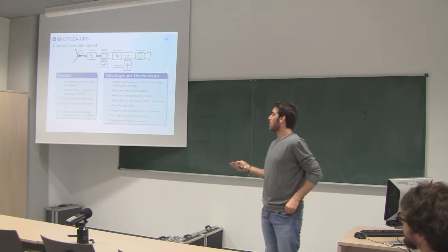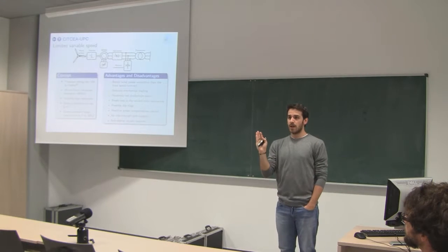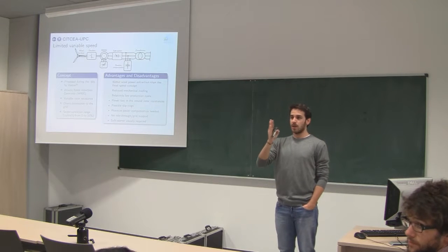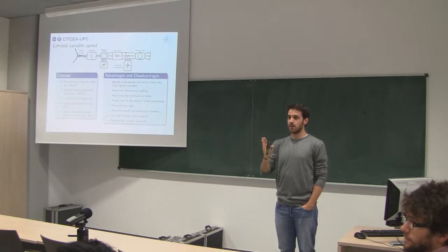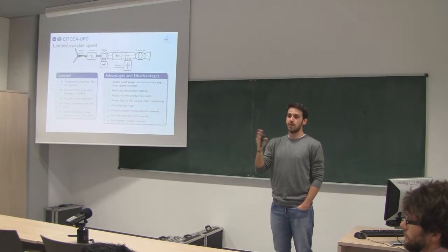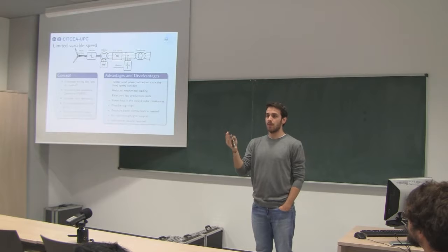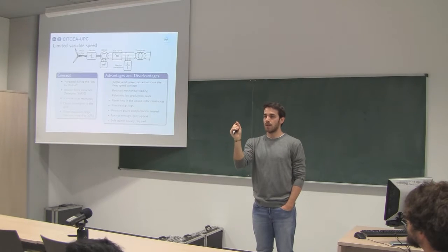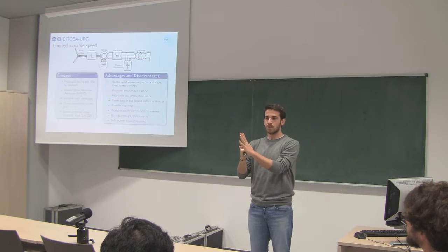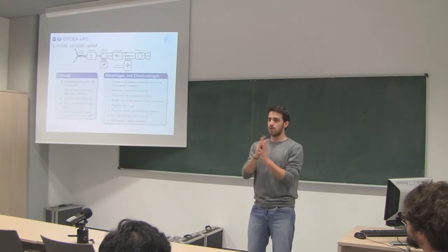Yeah, of course, but these are maybe the losses that they have on the resistors. You can extract more power than, for example, operating with a squirrel cage. You can imagine that the squirrel cage is operating just at a fixed speed, so it depends on the pair of poles, okay? But if it's operating at 1500 RPM, it could be producing less energy than, for example, this concept, because then you can vary the speed. Okay, you are having some losses on the resistances, but you still produce more power.